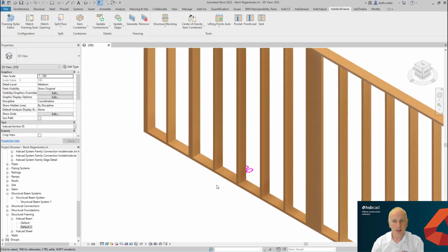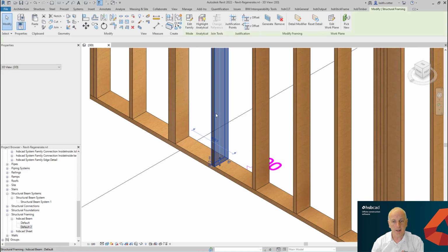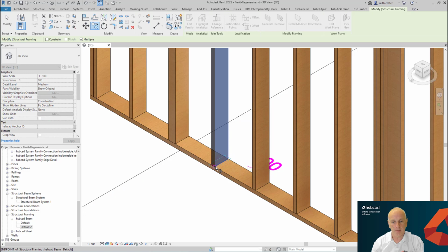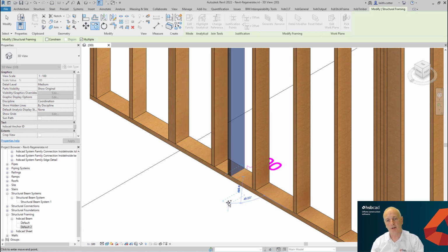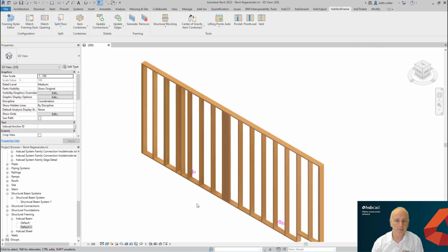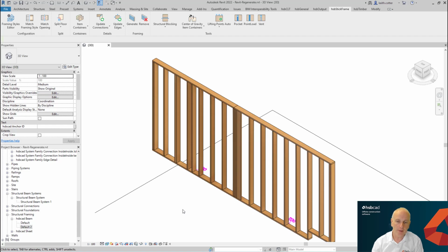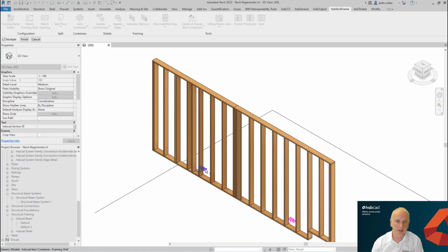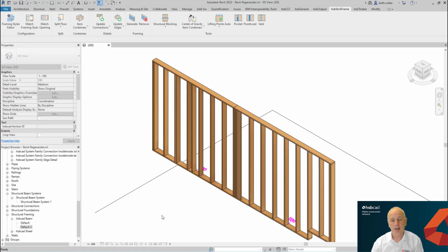What I'm also going to do is copy this particular beam to somewhere here to give me an extra beam in the solution. So clearly what I have just done is I've made some manual changes to the frame in this particular instance, in that I've enlarged this width of beam and I've copied another beam. If I now go to generate this particular frame and select this particular item container, you can see when it frames, it has now completely and 100% preserved the manual change.